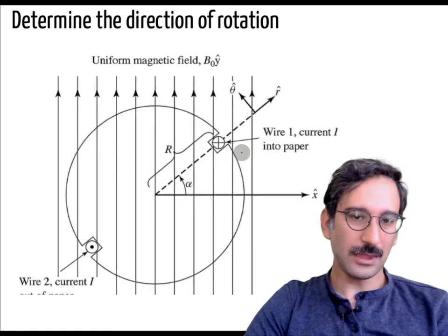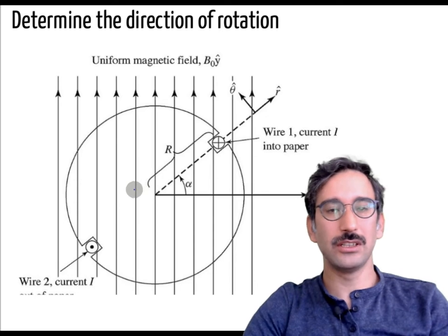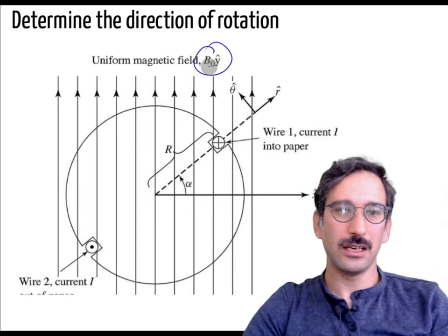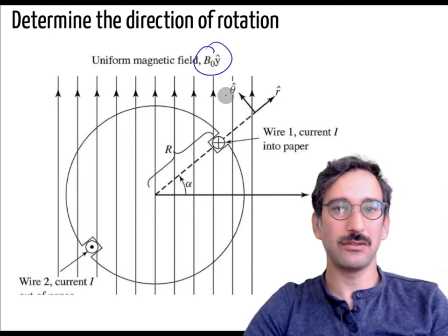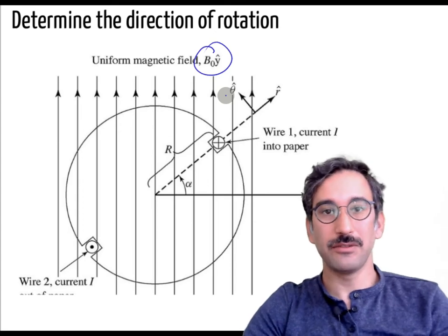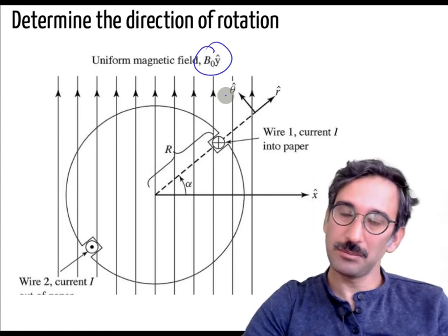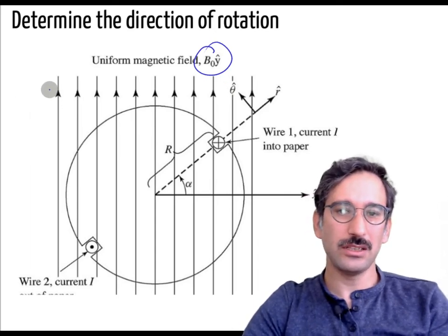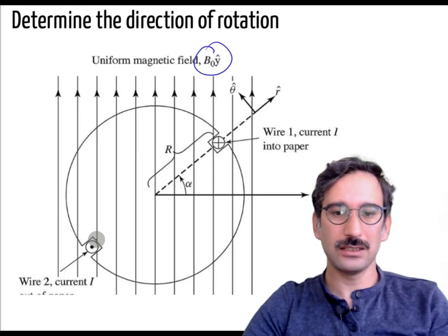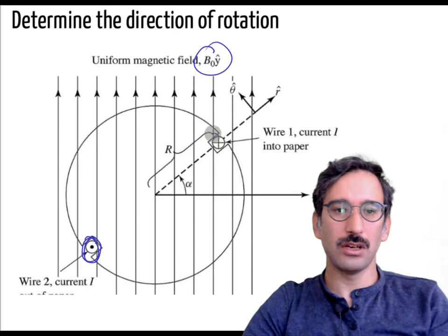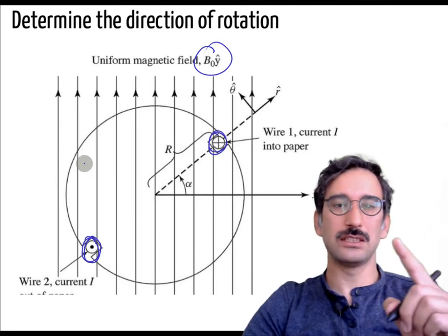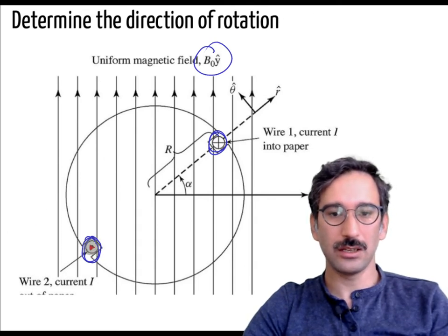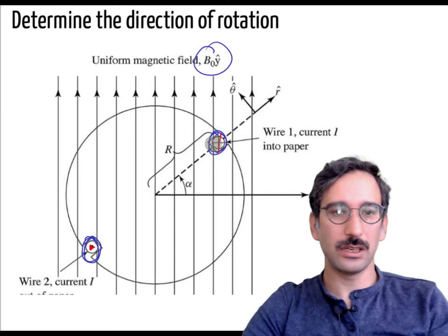But again, if you recall your knowledge of DC motors, a usual DC motor is a case where you have a B as a constant magnetic field, which can be created by field windings, which can be excited separately or connected in parallel, like shunt DC motors. Anyway, so you have some kind of magnetic field, and here you have two coils, like in a closed loop, so that one is coming out of the page and that one is going into the page.